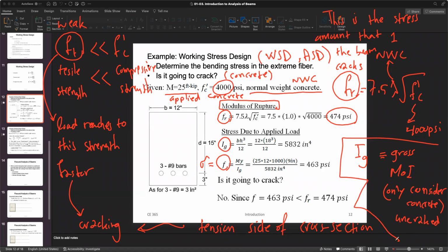All right. Why am I saying this? We're going to have a little bit of explanation in the next slide. But overall, we are assuming that the steel is very small. Look at the area of the steel compared to the area of concrete in the section. The steel is a very small amount, so we can ignore it and just safely assume the total moment of inertia is because of the concrete only. So we assume everything is made of concrete. That's it. All right. So if you are good so far, I'm going to erase the page and just continue writing on it.